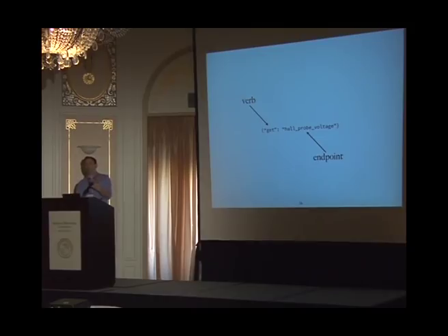So when we add a new instrument, we don't even need to stop our slow controls. We literally just change a value in a database, Dripline picks that up. The node that is responsible for that particular thing decides whether or not it needs to start any hardware, and then the next time you ask for that value, it simply goes through the same machinations that it would if it already knew about it and gives you the result.